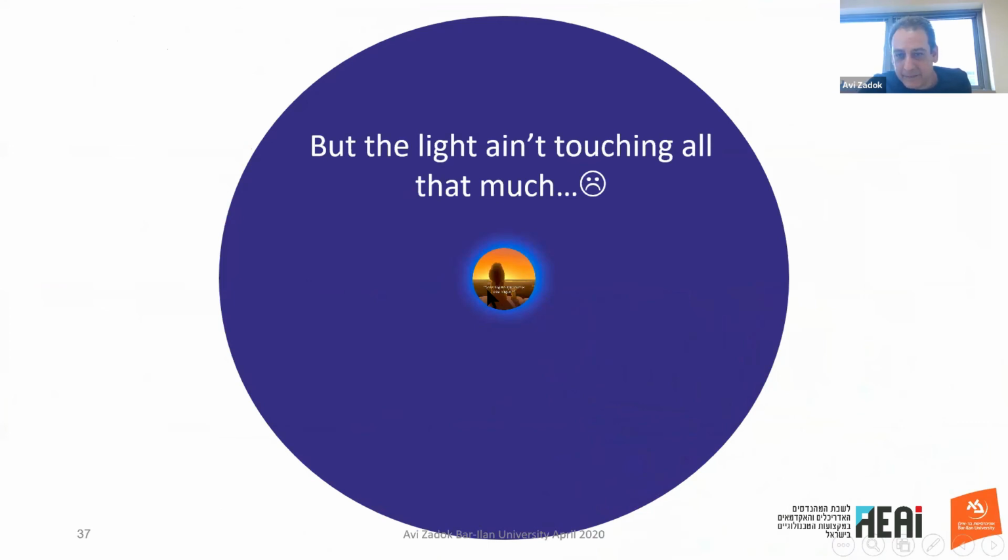And many times the things we like to measure lie outside a cladding that is much, much larger, so we have no touch with them. So I can measure temperature in Brillouin sensors because temperature prevails in the core. And I can measure elongation or strain because axial strain prevails in the core. But if instead we wish to measure a medium that is beyond the cladding, we cannot do it because light is here.